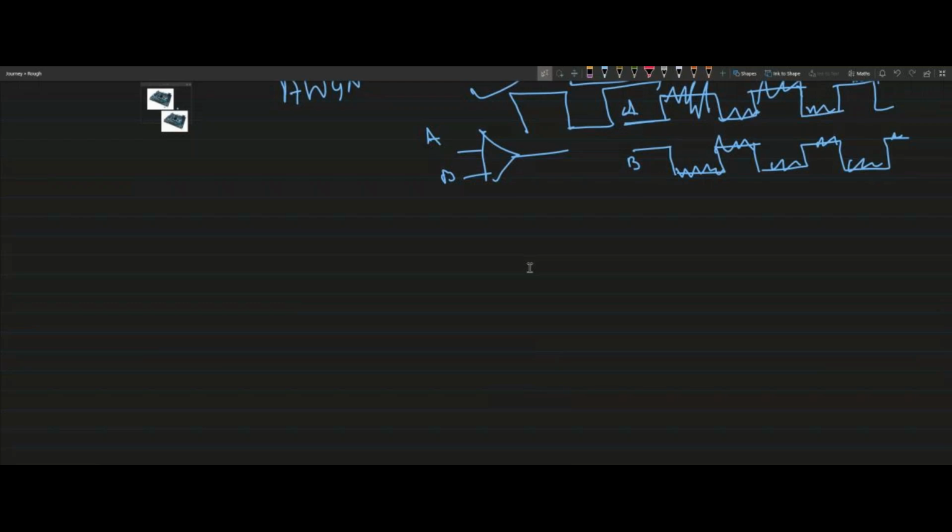In an ASIC we don't need any bit stream; we generate Gerbers, and after physical design, through fabrication, we manufacture it. Here, not through fabrication, we are writing through JTAG. That FPGA IC is already fabricated, and inside it all the lookup tables, block RAMs, memories and DSPs are already present. You are just writing the bit stream to those lookup tables, DSPs, or memories in such a way that the FPGA will act like the circuit you want. But in an ASIC you are designing the circuit itself.